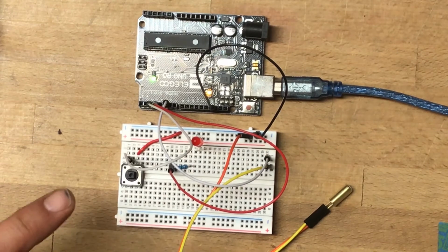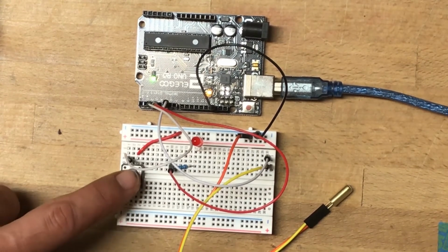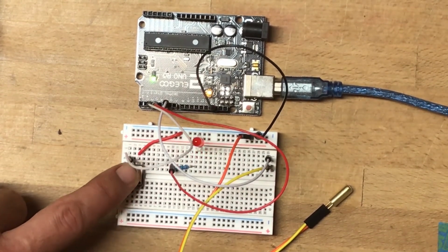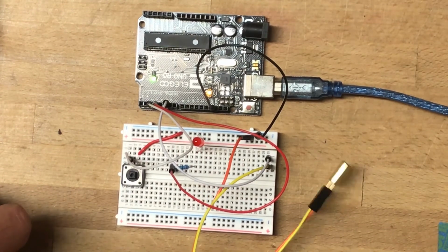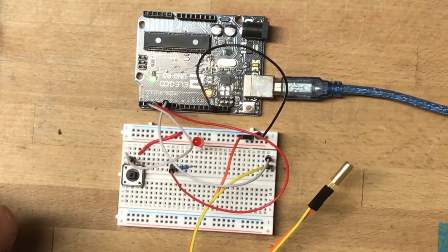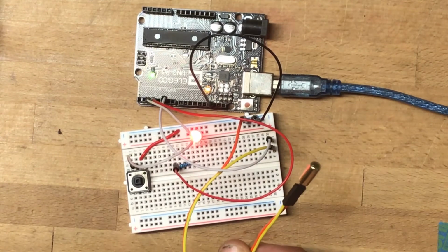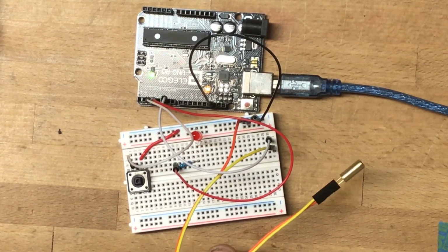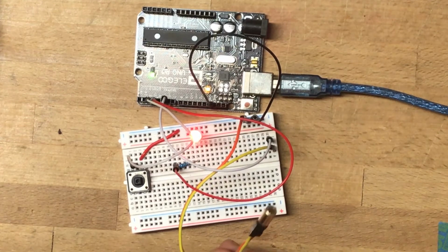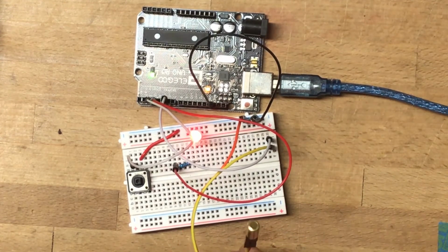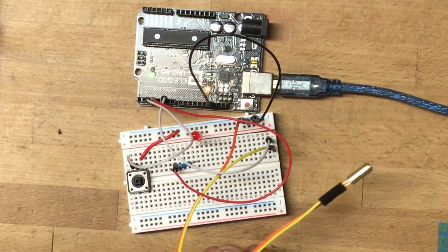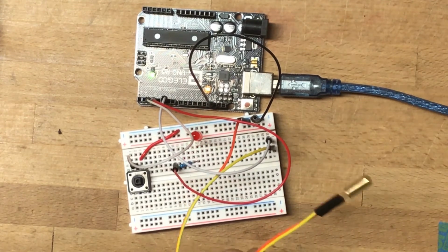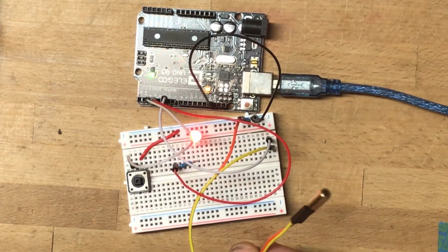On this circuit I've got two switches set up. I've got a simple momentary push button switch and a tilt switch. Mine looks gold, some look black. It's just a cylinder with two leads going to it. I have it connected back to the board with these little jumpers, but depending on orientation it'll complete or disconnect a switch. You can usually hear a little ball rattling around in there. That's what's rolling around to complete the circuit.